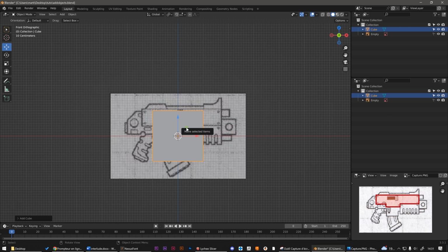And that's it. To finish the fore end, we can see that there is a part below there. I don't know what it corresponds to, but we are going to model it because it will fill in a hole we don't want. So I duplicate this object here, then move it along the axis about here. And then with SX I change the width, and I'm going to move it here. We're going to make it less thick with SY. And that's it.